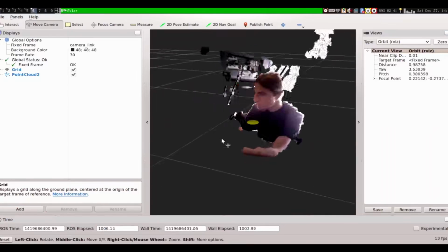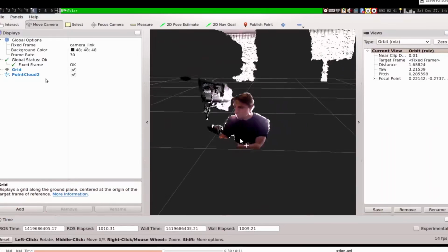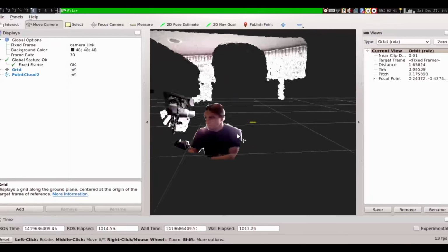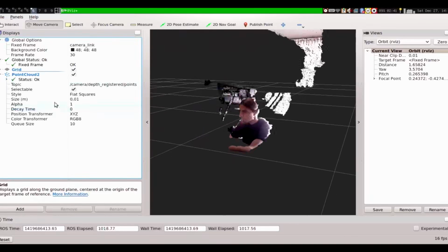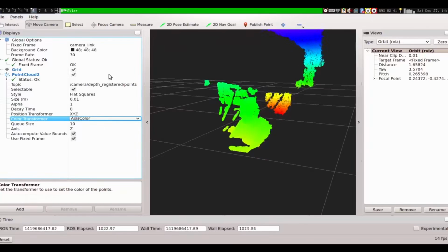So you just start RViz, add this point cloud plugin to it, tell it on which topic to listen, how to do the color transform, and then you have 3-dimensional point clouds introspectable by the human developer who needs to debug what's going wrong at the moment. And writing something like this viewer by hand, I can tell you, takes you more time than you planned to spend on your whole hobby robotics unload my printer project.